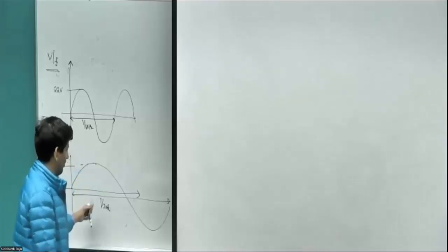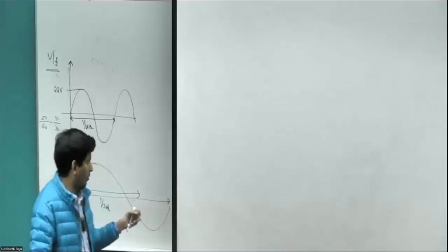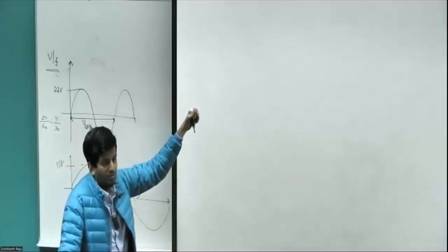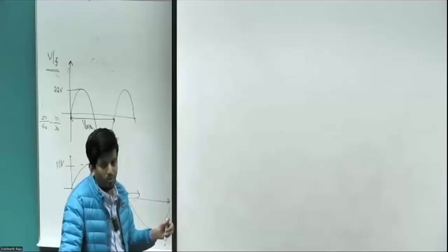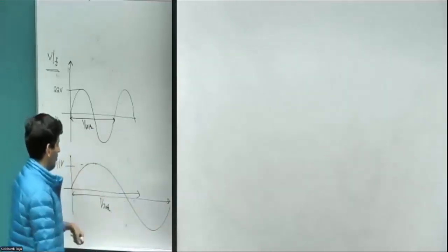This is not always strictly followed. For instance, when you go to very large frequency, that would also mean that you need very large voltage, but we have a limited DC bus voltage. So there comes a point where the DC bus can't generate any more voltage and the motor will go into a mode called flux weakening. But we'll ignore that extreme scenario.